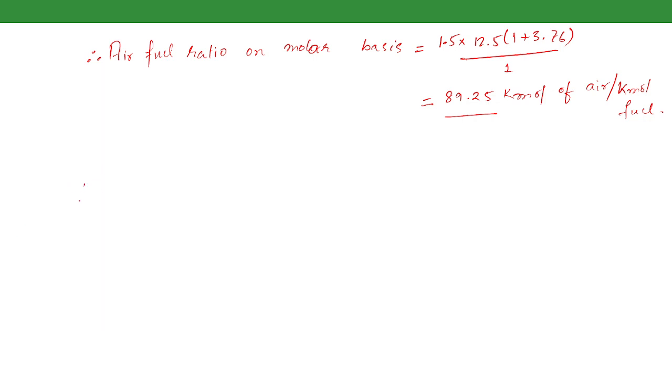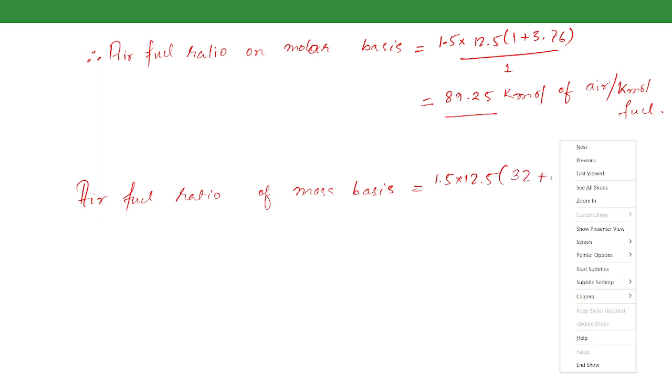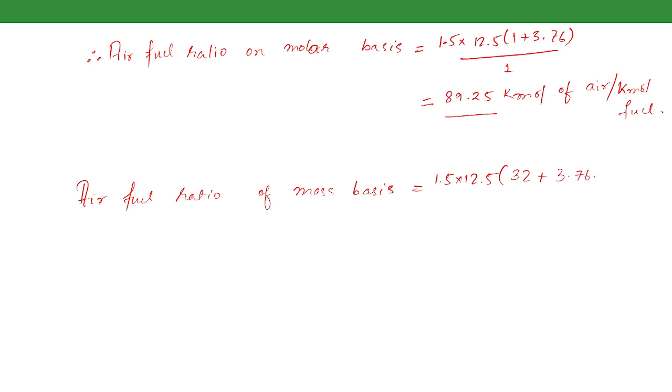Also the air fuel ratio on mass basis will also be the same, that is 1.5 times of what it was previously. So this is 22.58 kg air.